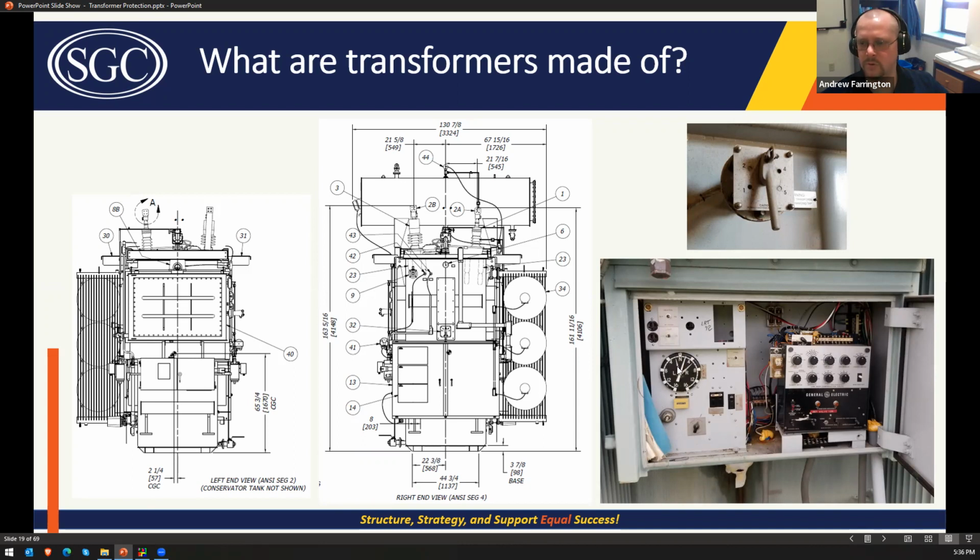It's kind of just like the regular dial, but it's got a little pin on it, such that when the dial that tells you what your actual position is moves beyond this hand, it'll move that hand with it. And then it'll go back and that hand will stay. This shows you the range in which this particular transformer is operating.